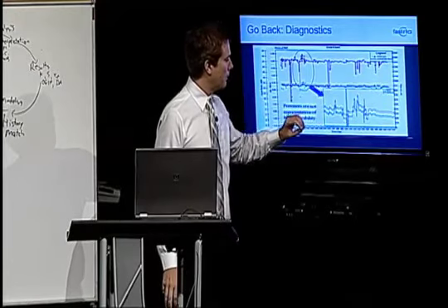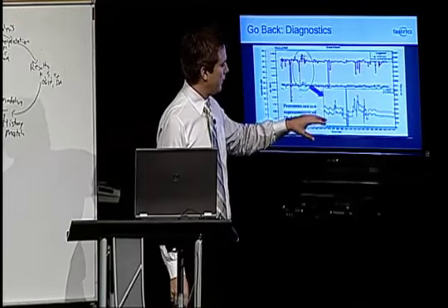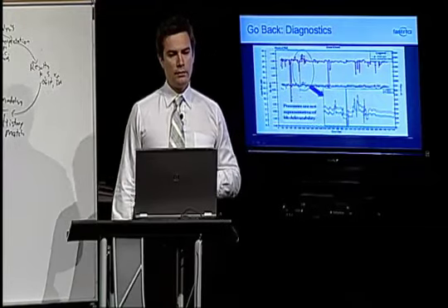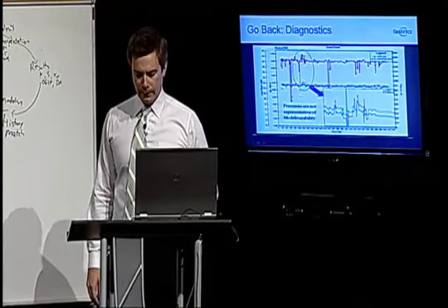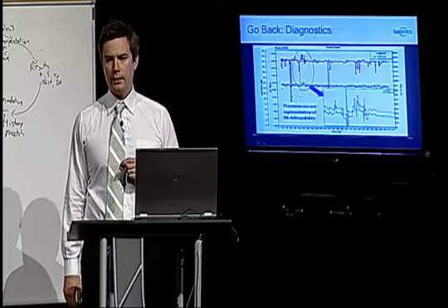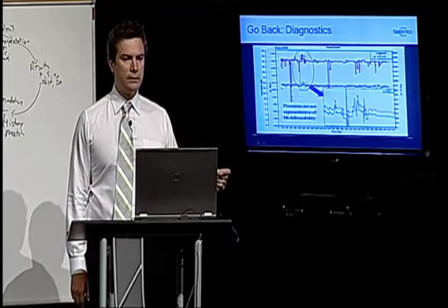So, moral number one, or moral of the story: don't use pressures that are measured on the downstream side of a choke. In general, you want to use flowing pressures that are as close to the source as you can. What's the source? The source is the sand face.